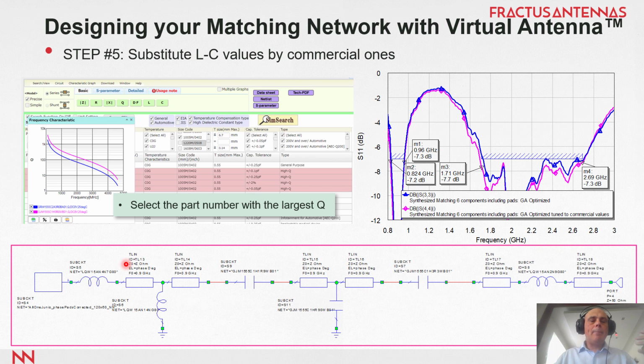So at the end, the matching network, that is the synthesis, also takes into account the path effects, as well as you can select with the software to use available commercial components. In this case, we're using components from Murata. So you can see here, this is 1, 2, 3, 4, 5, 6 components of the matching network with the part numbers. So these part numbers are the ones that we are going to take from the simulation, bring to our device, and test in our device.